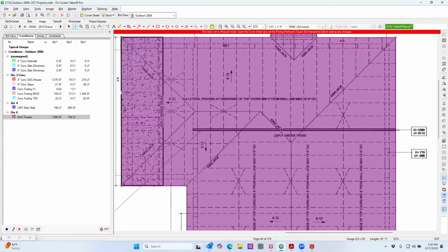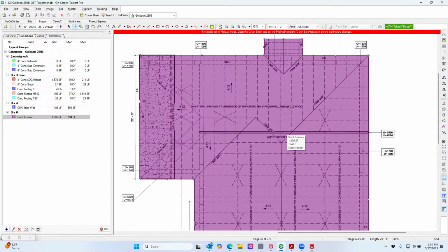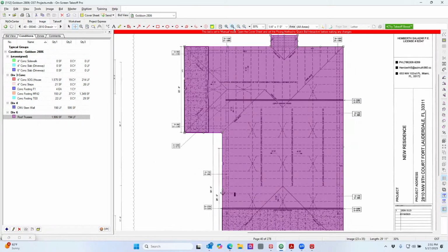So you have to run at the top chord of that truss. You have to run a 2x4 and nail it all the way across from one end to the other. Now, though this is shown here on this set of drawings, what happens is you get something called shop drawings. So there's actual engineering provided by the truss manufacturer. You have to install it per the truss manufacturer, not necessarily the structural drawing. So if you have a conflict and you're not sure which one to go by, you can always ask the engineer through an RFI, but your rule of thumb, you're going by the shop drawings, okay? Because the person that manufactured the trusses, they put separate engineering together normally for that.